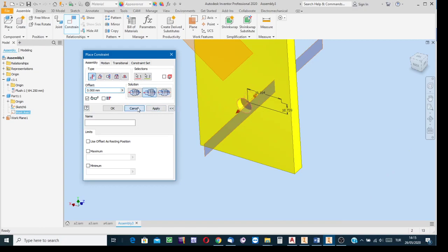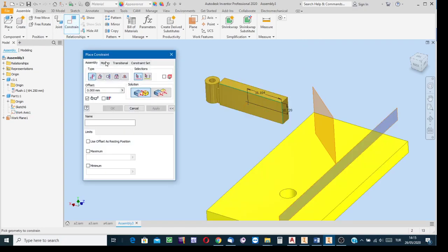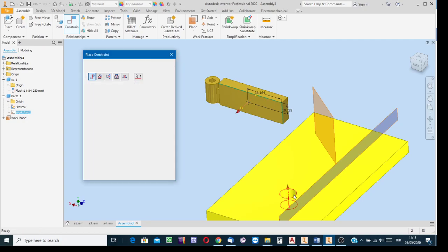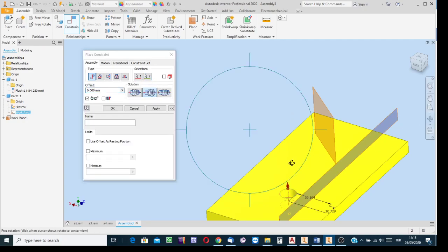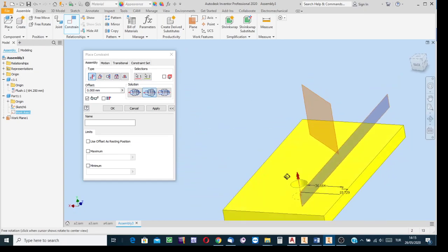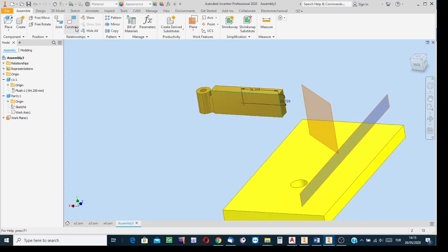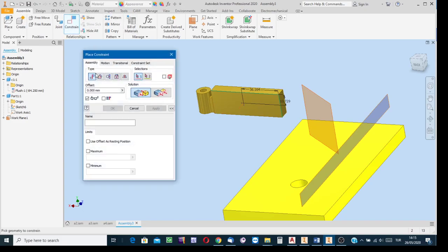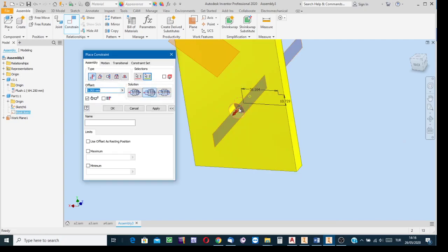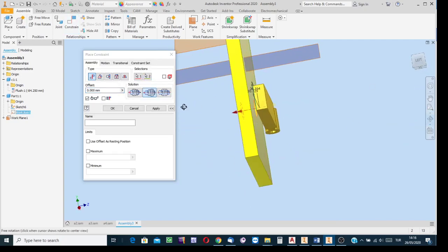And the axis of the hole. Do it again. Constraint. Select this type. Indicate the work axis. Indicate the longitudinal axis. Yes, now these are in relation. The axes are in alignment. If you change the order, the firstly indicated one moves, the secondly indicated one stays at its existing place. With this type, indicate the edge of the hole while you are seeing the longitudinal axis simulation. Indicate the work axis, and then yes, now the axes are in alignment.